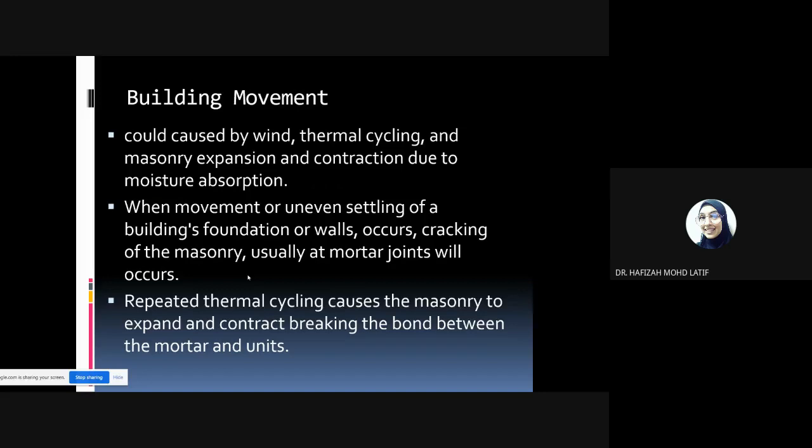In Malaysia, we have plastering on most of our buildings, I can say almost all. Even if we have that facing brick look, sometimes it only looks like bricks, but it's actually a finish, a type of tile that looks like bricks. So it protects your mortar joints. That's the pro of having plastering and building facades on your bricks.